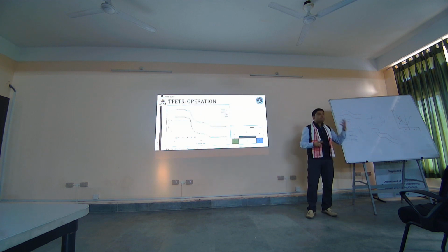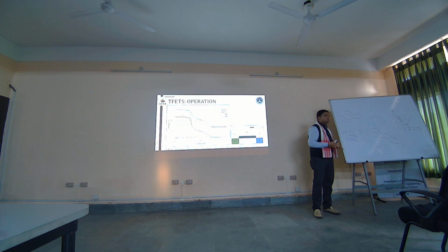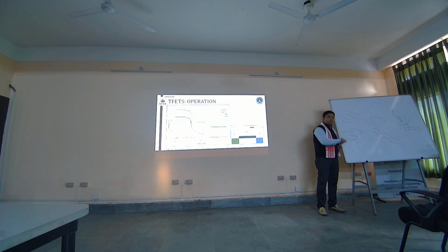Okay, this is how we can reduce ambipolarity in tunnel field effect transistors. Of course, there are other articles which have explored other methods of doing that, but these are the most widely used ones, and these have almost become standards. So when we start with designing a TFET, we usually incorporate this in the first go itself. Okay, the gate drain underlap and asymmetric source drain doping.